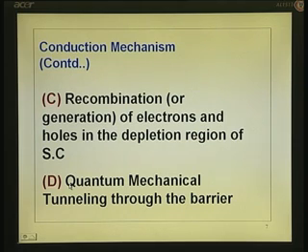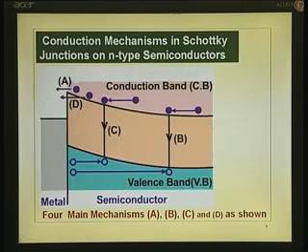So, B and C, what we have discussed just now, are both the same. Ultimately, if it is the forward bias case, go back to the diagram. In part B, the recombination is taking place in the neutral region. Here in C, the recombination is taking place in the depletion region. In the reverse bias case, this is absent, and this will be a generation current, the opposite.